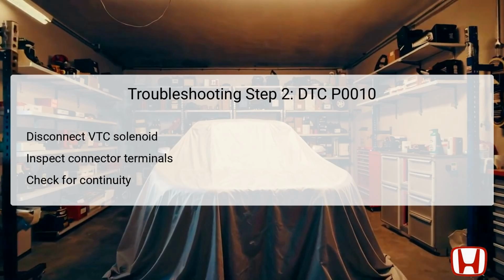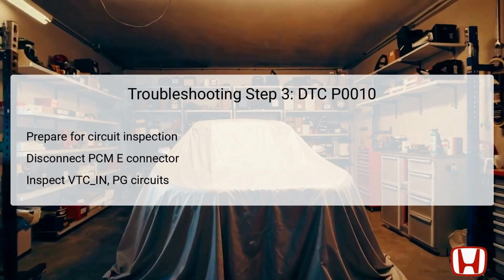Ideally, the resistance should fall within the range of 7.01 to 7.75 ohms at room temperature. If the measured resistance deviates from this range, it indicates a fault in the solenoid itself and suggests that replacement is necessary.